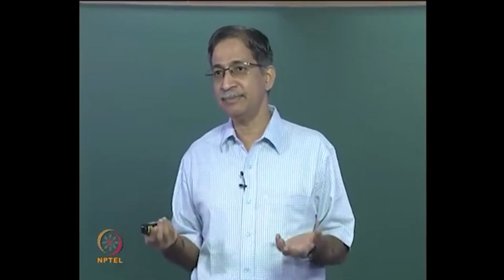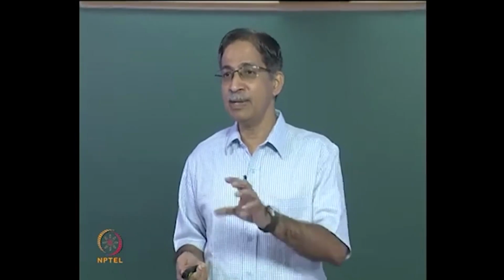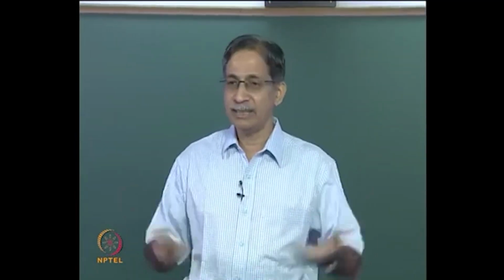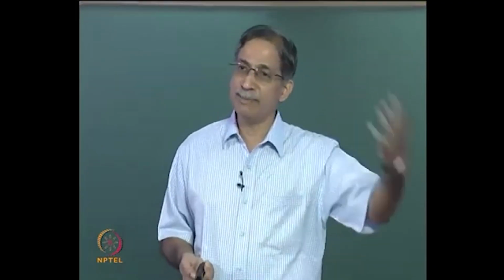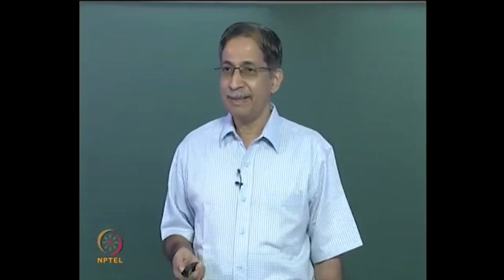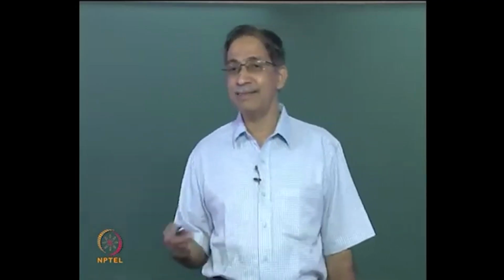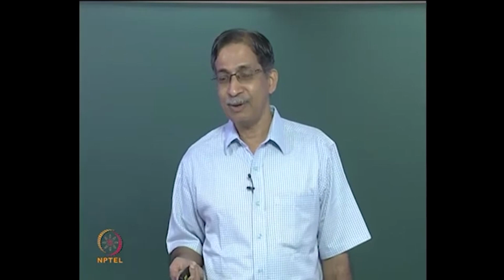So that's it. We are now ready to solve any problem. If someone were to give us a value of P, you just have to modify the stiffness and do the same old thing. Okay, but this also gives us a way of finding out the critical buckling load. How do you find the critical buckling load?